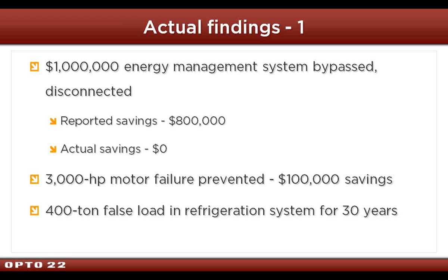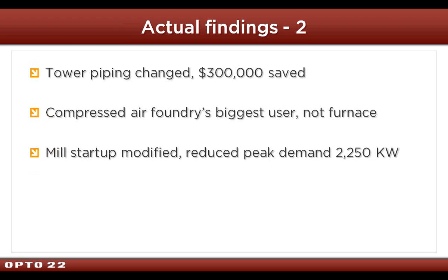Actually, Opto just published a case study on this Mariah packing plant. But for 30 years, they've been running it. The refrigeration people, their own people, had not found this problem. This is not uncommon. I was working in a hospital over in Connecticut, and they were getting ready to spend $300,000 on a new cooling tower. They couldn't get the return water from the tower cool enough to keep their chillers and their chill water low enough to maintain humidity in the hospital.